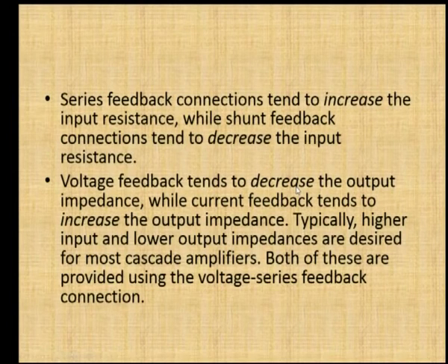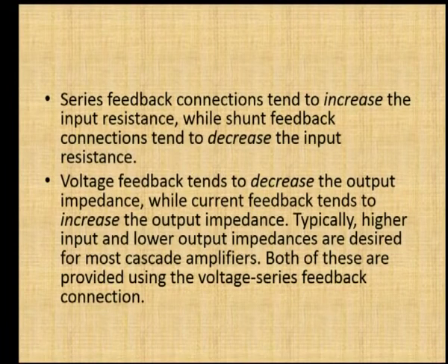Series feedback connections tend to increase the impedance. Wherever you have a series connection, it will increase the input or output impedance, and a shunt connection will decrease the impedances. Voltage feedback tends to decrease the output impedance, while current feedback tends to increase the output impedance.